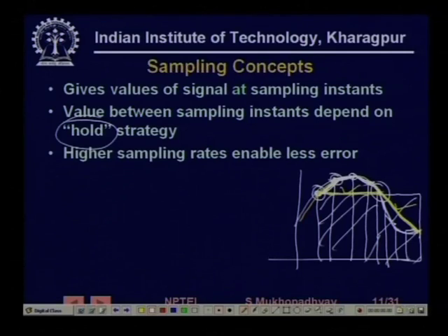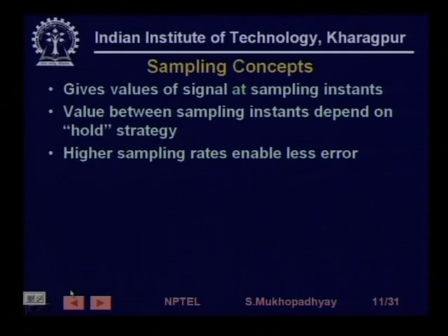there are certain fundamental principles to be obeyed, because ideally speaking you would like to sample at the lowest possible rate while trying to keep the error low, and especially you would like to keep the high frequency errors low. You may have some high frequency errors, but generally you want the low frequency errors, that is, let us say, the average values over certain time intervals etc., to be pretty accurate, right. So, generally the low frequency component of the signal is actually of more use for the purposes that we are discussing, and so we do not want low frequency errors, right.